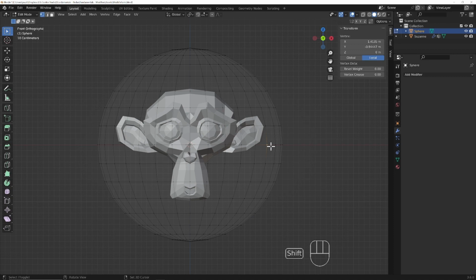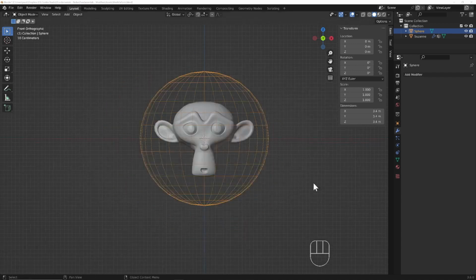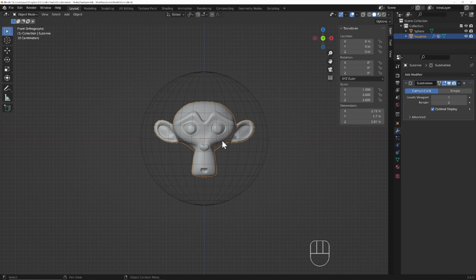It's important to note this modifier is entirely dependent on the order in which it appears in the modifier stack. In general, you will want to have this higher in your modifier stack, as any modifiers placed above it will cause the modifier to unbind when their parameters are changed, and a lot of your work could be wasted.